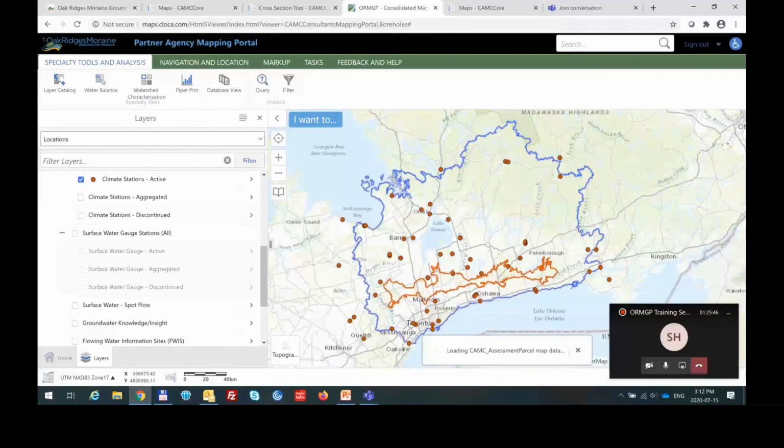And over on the western half, more reliable in the sediments, say from the lower Newmarket Till up, versus the deep system, which is infilling this deep Laurentian trough, because we simply have fewer boreholes that go to depth across 250 to 300 meters of sediment infill along that valley. So really extreme thicknesses of Quaternary sediment are more unreliable than the shallow subsurface, just because few boreholes go down to that depth.